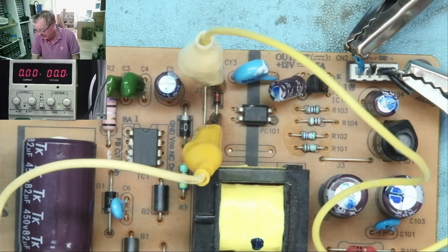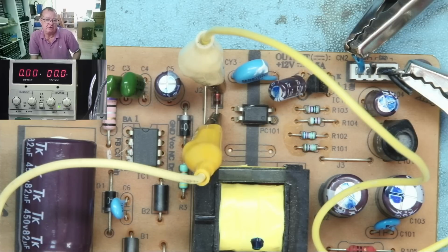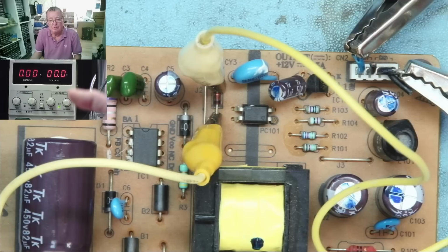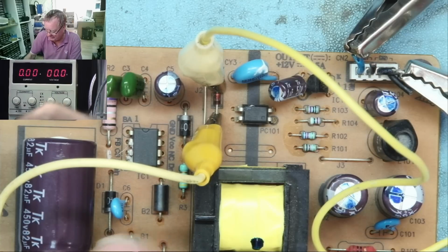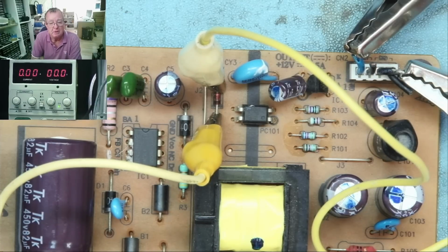Okay guys, so that's how I test them. Now you should really know all about the TL431. It's not a mysterious thing. It's just effectively a Zener, which you can vary the voltage output by using 2 resistors, or just connect the reference to the cathode for 2.5 volts. You've seen how this circuit works. You can clearly see that with the Zener or TL431, the LED turns on at exactly the point you want it to do and sends a signal back into the other half of the circuit to regulate the output voltage. Hope you enjoyed that, and I hope you really think that is all you need to know about TL431 to fix stuff.